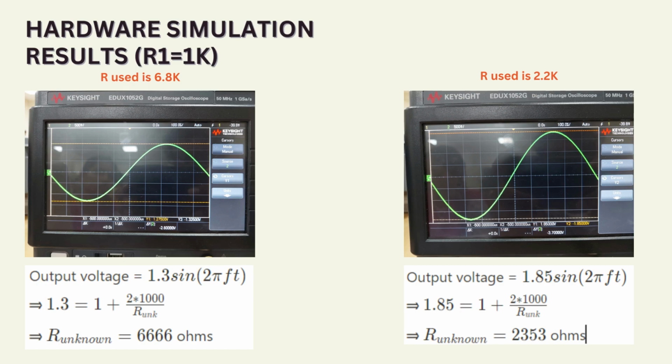It has around 0.05 volts, but for a larger unknown resistance, if you are taking a measuring range of 100 kilo ohm to 1 mega ohm, these small changes will affect a lot when we are trying to estimate an unknown resistance of 800 kilo ohms, 900 kilo ohms. These small 0.05, 0.01 voltages show significant error as we go ahead in the measuring range.